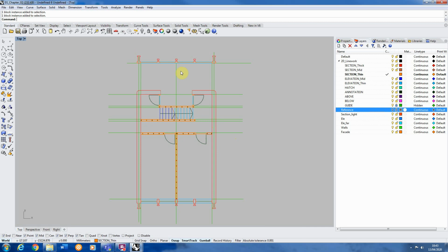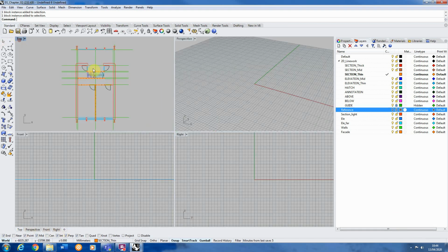So we're going to start this session by setting up a basic A3 layout page. And layout pages in Rhino are found down here just on this little plus tab at the bottom left hand corner of your page. Usually you'll have a window for each of your different views you've set up in Rhino, and these correspond to these four windows you start with in your views. So this plus icon here, if we click on it, we can either split our viewports as such, or we can create a new layout, which is what we're going to be looking at today.